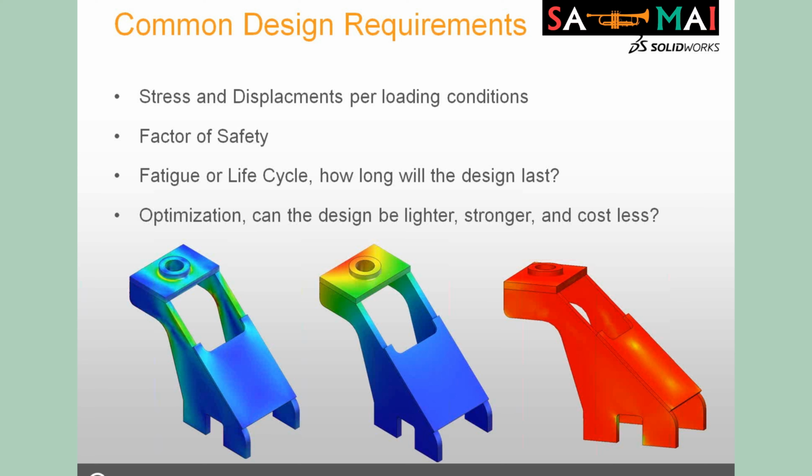Another design criteria would be factor of safety. A lot of times you have to meet or exceed a specific factor of safety of 2 or 3 just to make sure that your design is safe. Another thing that designers or engineers should be concerned with would be fatigue or life cycle. How long will the design last? Unless it's a one-time use throwaway item, we need to make sure that it's going to last through a number of cycles, so 1 million cycles or 100,000 cycles. You can also look at fatigue on the opposite side and design your part to specifically fail at so many cycles.